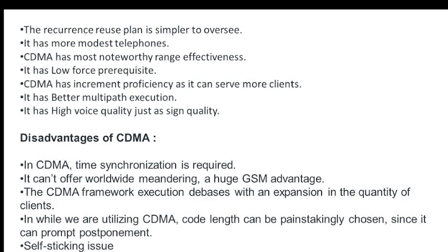Some of the disadvantages of CDMA are: in CDMA time synchronization is required. It cannot offer worldwide roaming, the huge GSM advantage. The CDMA system performance degrades with an increase in the number of users. While we are using CDMA, code length must be carefully chosen since it can lead to delay. Self-jamming problem.